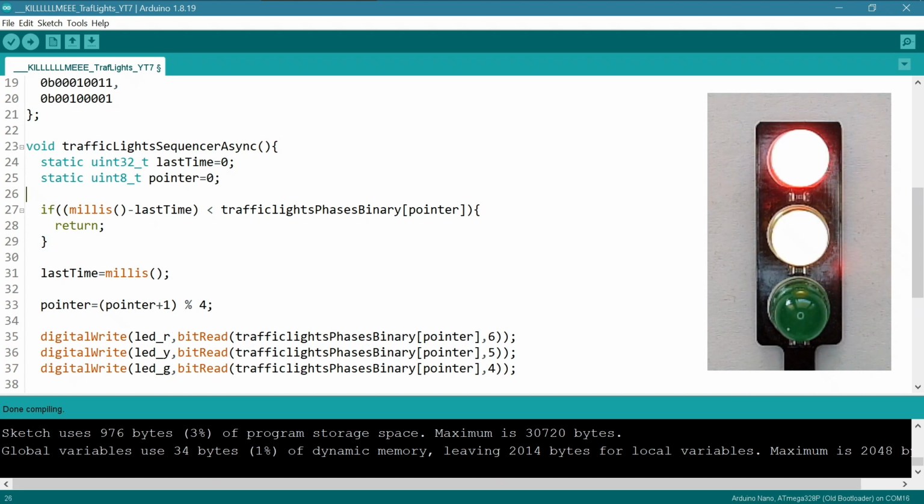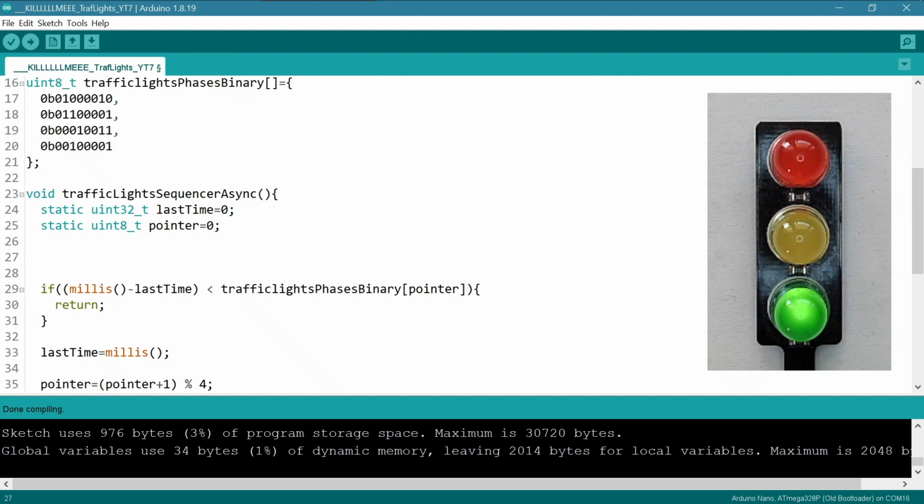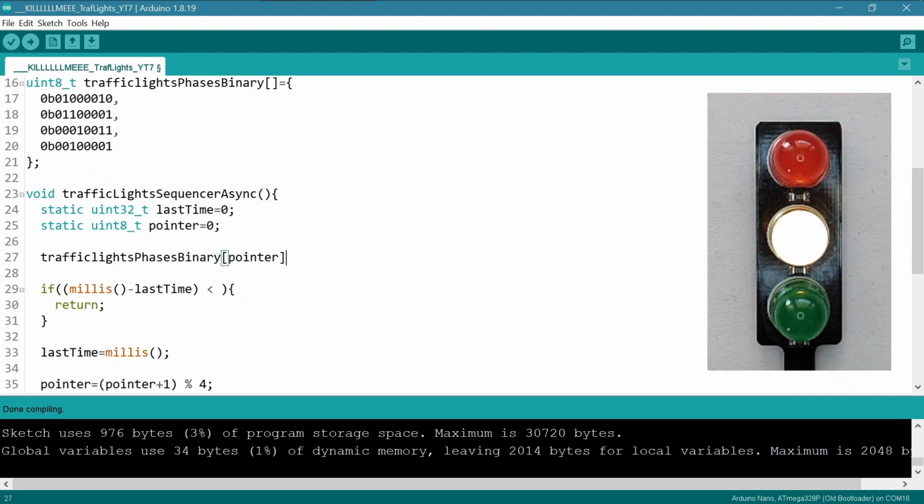All right. I'll need to do something about the delay because the delay now is binary coded over here. So we have to get from binary to something our delay here can use. So let me grab this one. Put it over here. And let me drop this stuff into a variable so it's easier to read. I won't do the multiplication over here, so I can go for uint8_t type, and let's call it interval. Equals not this, but what we can do here, if I leave it this way, we would have the upper 4 bits in our interval. We don't want to do that.